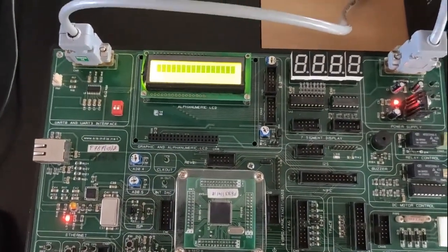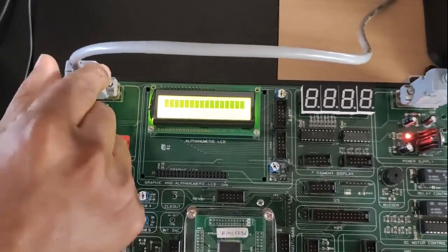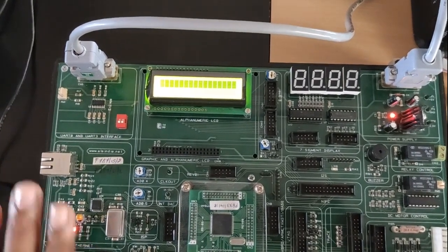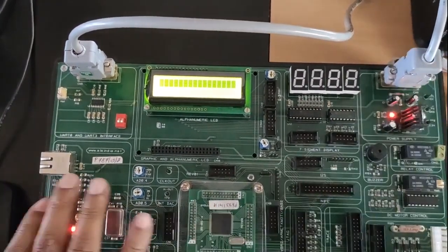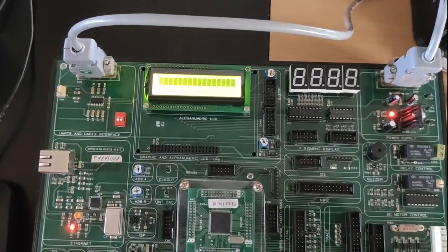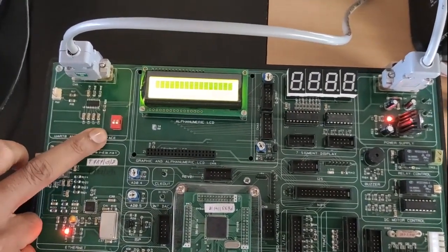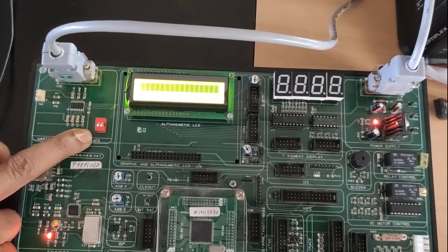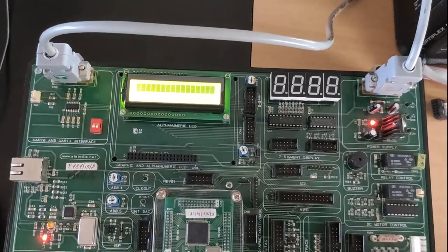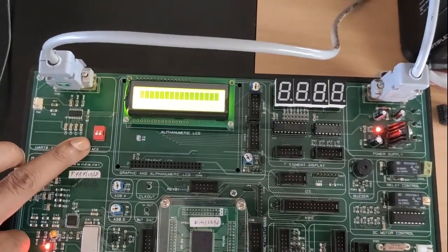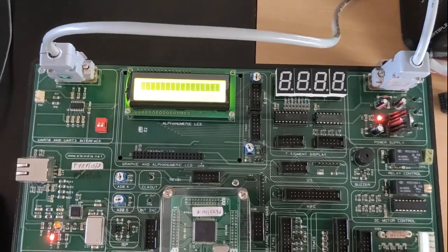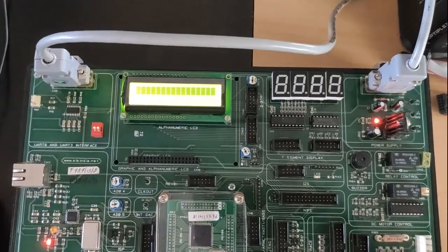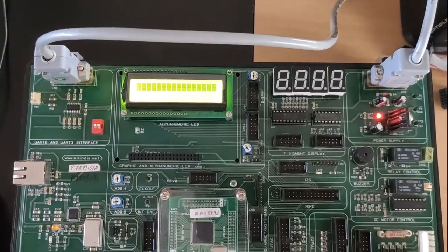So for connections, FRC is not required here. Only the communication cable which works as UART mode for this experiment is good enough, and this is the power supply as you did. Now the important part of the experiment here is switch 21. As I said, switch 21 works in dual mode. If it is in on condition, it will download the hex file into hardware. If it is in off condition, then it works for UART. So this experiment belongs to UART. So now I'll switch off switch 21 and I'll reset my code.